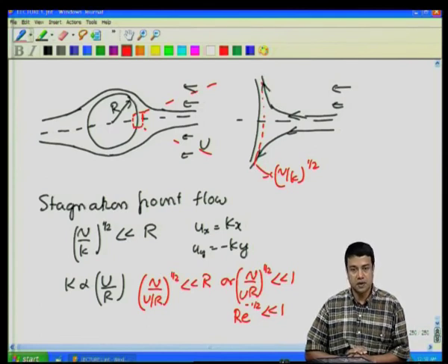In this particular case, it turns out that the momentum conservation equation is nonlinear in the velocity field, and for that reason not all mean velocity profiles can be reduced to a boundary layer solution. There are only specific forms of the velocity profile that can be reduced to a boundary layer solution.